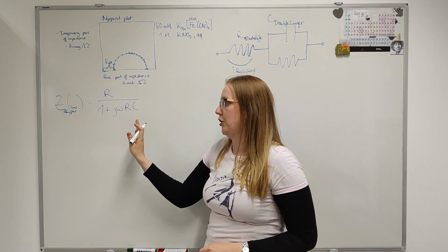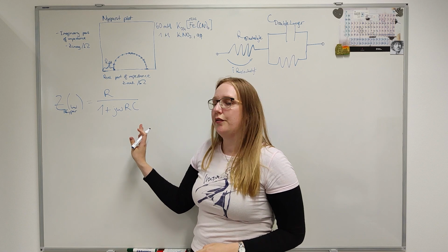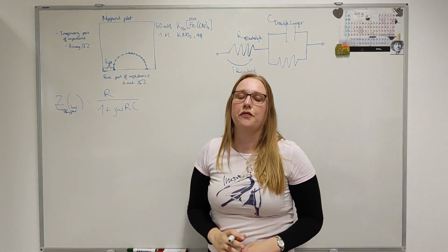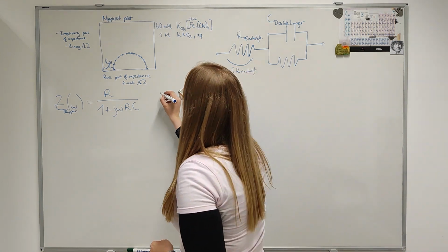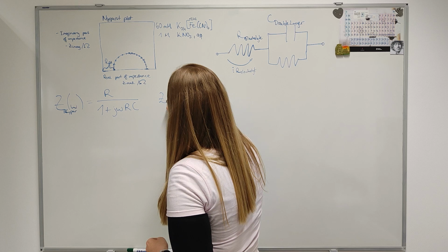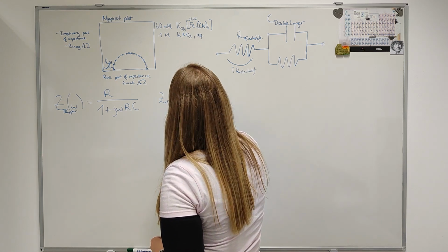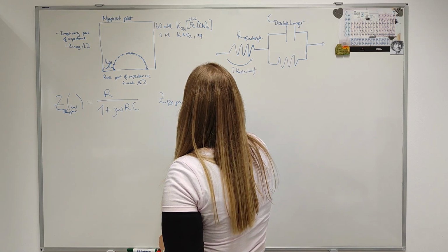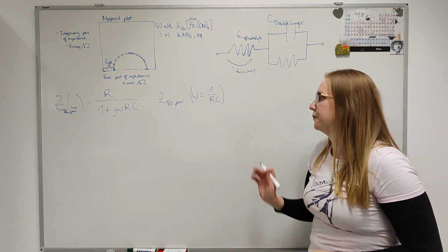So we have our general formula for the parallel RC circuit here, and as we have seen, we often can already gain a lot from this if we look at the value of the impedance for specific frequencies. So let's see here what we get for this impedance if we consider the inverse time constant, 1 over RC, as characteristic frequency.